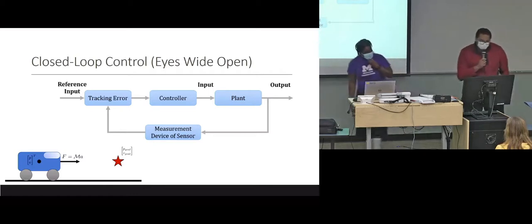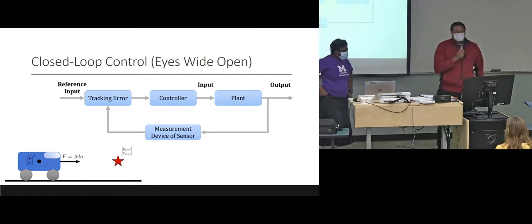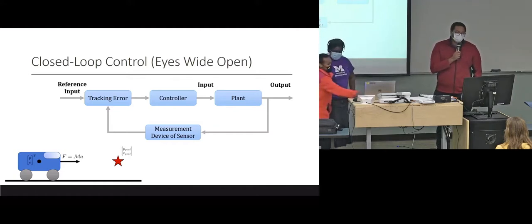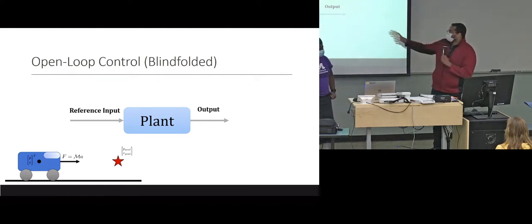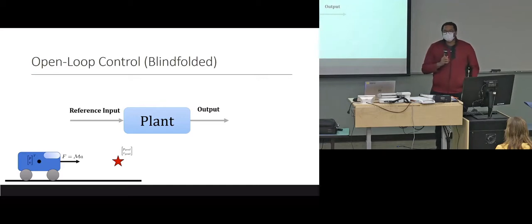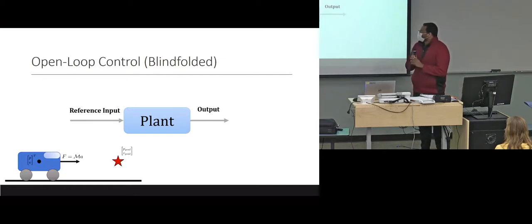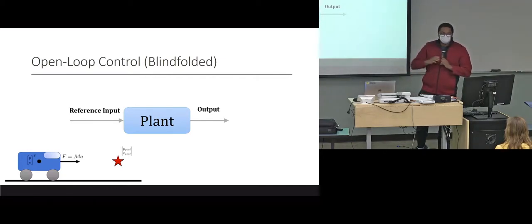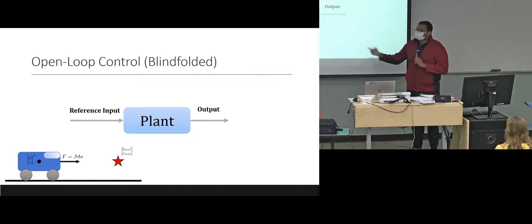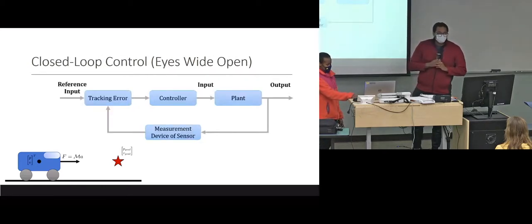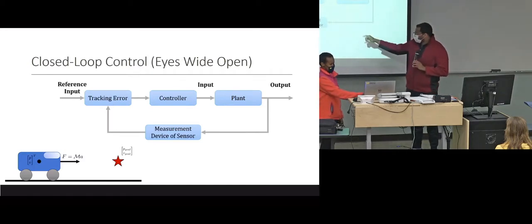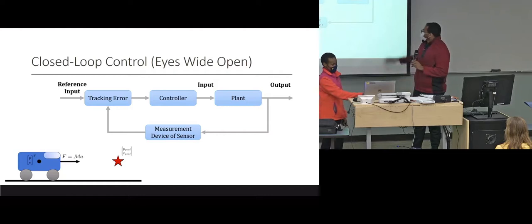Yeah, so exactly. It's open loop and closed loop. The open loop has no type of feed forward or feedback term. You're simply running something through the plant, which is a fancy term. If you want to look cool and talk to controls people, you say, I'm running something through my plant. I don't really know where the term came from. So with open loop control, there's no feedback term. There's no information of where you currently are. You just apply your torques and hope for the best. But you're exactly correct. With closed loop control and this model predictive control, you always have this loop back. So after we pass our input through the plant, we actually figure out, okay, I applied a throttle force or something.